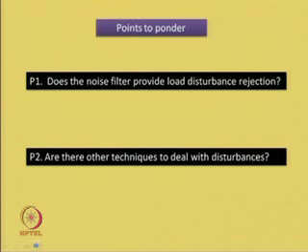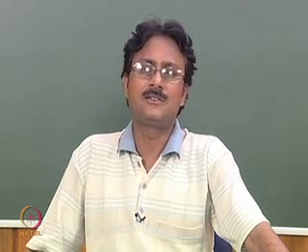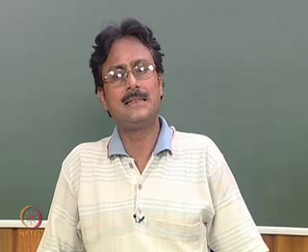Yes, the noise filter, whose primary job is to reject the ill effects of noise inputs to the systems, can also provide satisfactory load disturbance rejection, but that may not be true always. Therefore, it is always necessary to design some load estimator and controller in a closed loop system.